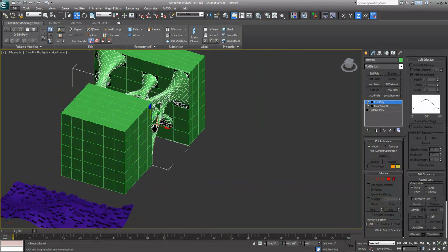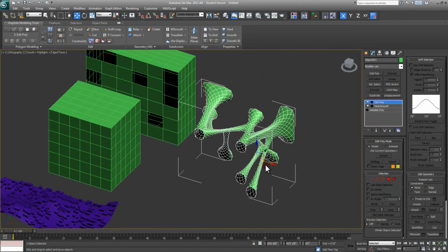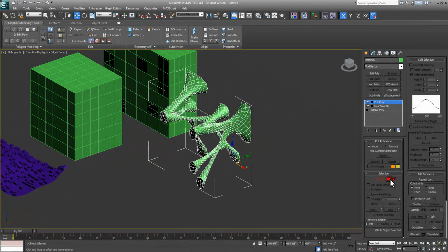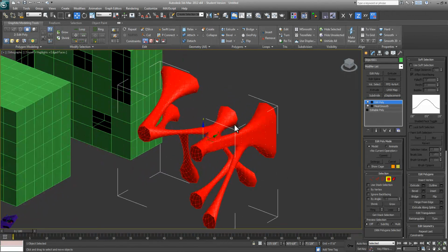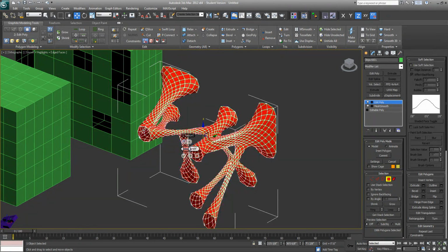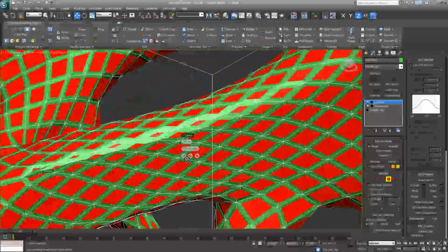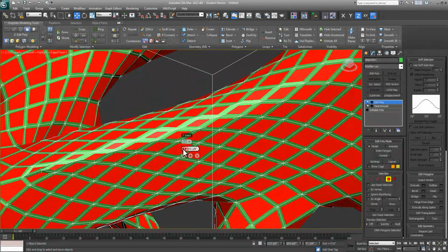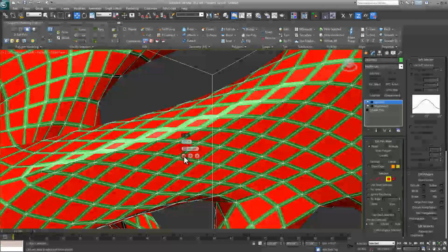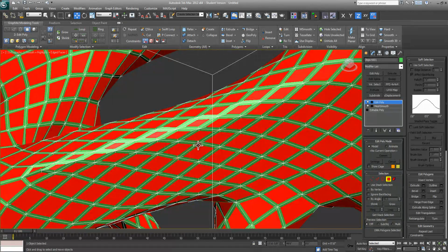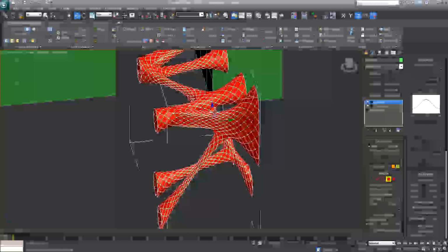Say I then take this and just do one last step here. I'm going to go back into my polygon sub level, and I want to take these surfaces and inset them. So this is under the polygons, and I'm going to do it by polygon, and I just want to inset these guys. We'll say 2/8 of an inch. My scale is kind of off here because I'm just doing this arbitrarily. But I'll click accept.